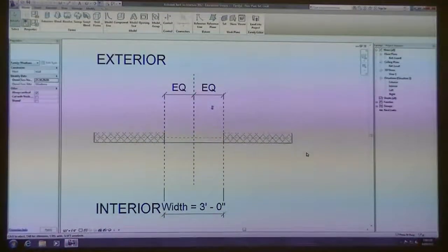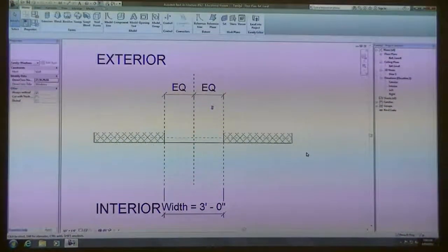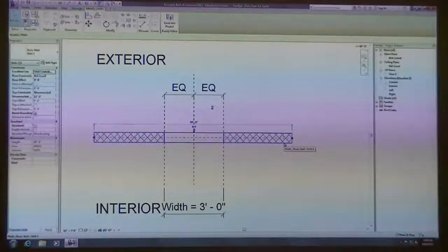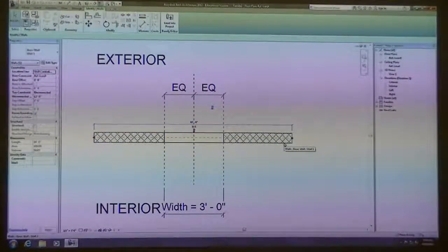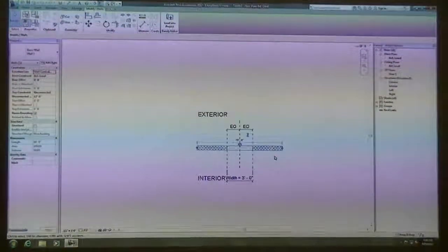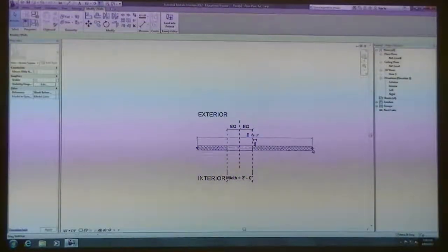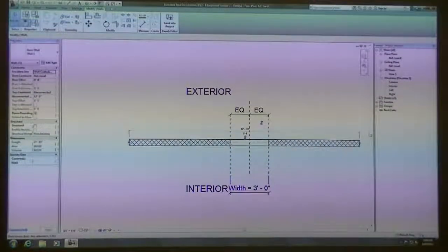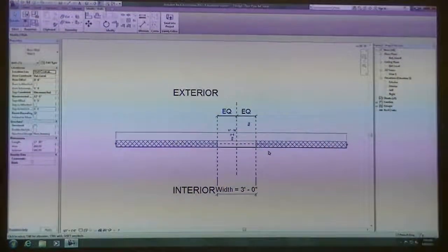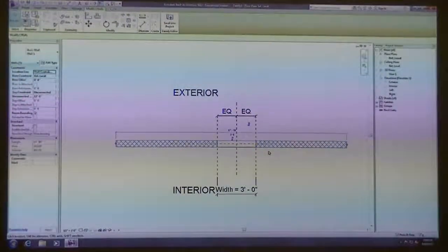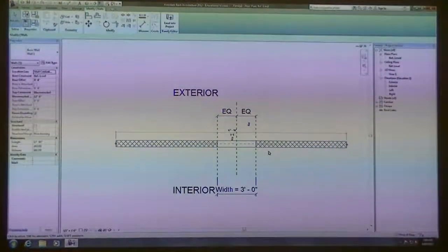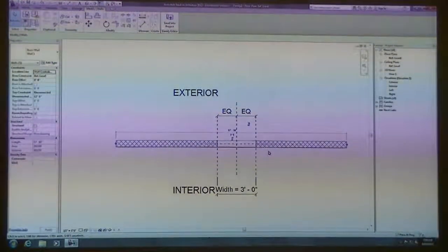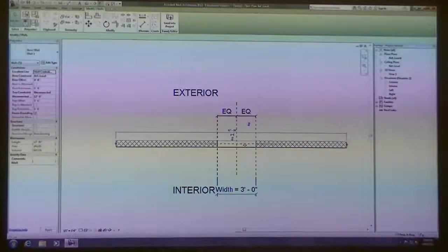Now the window template basically comes looking like this. It has a wall. This should be kind of similar to the door exercise that we did. I think we just kind of looked at a door. We didn't go into a whole lot of detail. But the wall that is in this particular model is just a default wall. It's just a template that is showing how this window is going to interact with the wall. And then once we bring this into our Revit environment, this wall disappears and only the window remains.